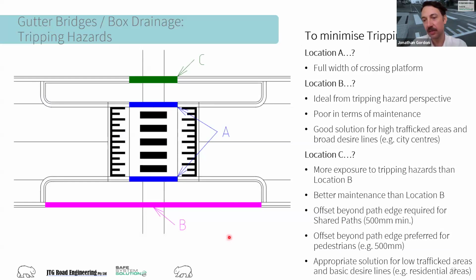That's right, grates can be removable. If you're using more standard box culvert style arrangements, then they might be harder to remove, though. You can also have grates that are lockable, so they're not able to be stolen. There's various proprietary systems out there. And Pru's added in a bit more context around extending the grate as you need, and I think you've covered that nicely with these diagrams where you're extending these sorts of things.